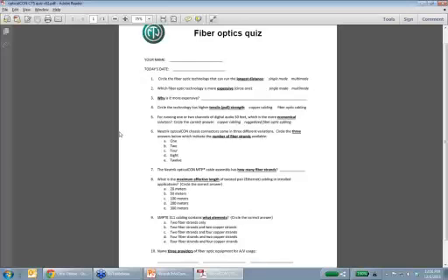Which technology has a higher tensile or pull strength? Remember, fiber optic cabling can be pulled much harder than copper cable. Question 5: for running 1 or 2 channels of digital audio 50 feet, which is the more economical solution? The answer here is copper. At 50 feet you're under that 100-meter limitation, and you're only running a couple channels of audio, so you don't have to multiplex a tremendous amount of data. So do it over copper. No need to use fiber in this case.